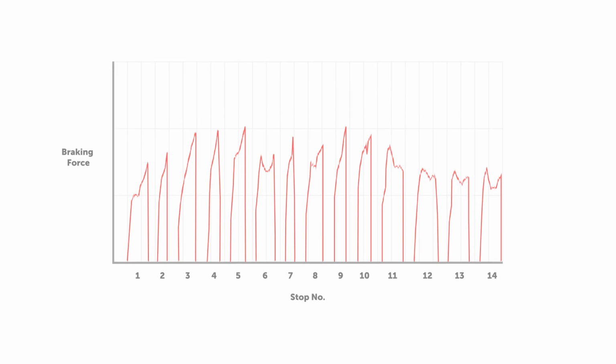As the stops continue and the brakes heat further, we can understand how the brakes fade with high temperatures. In an ideal situation, the brakes wouldn't fade, but there's always going to be some temperature range that we need to stay inside. Fade can be recognized by the pedal feel remaining firm, but the driver has to apply much more pedal force to slow the car at the same rate.